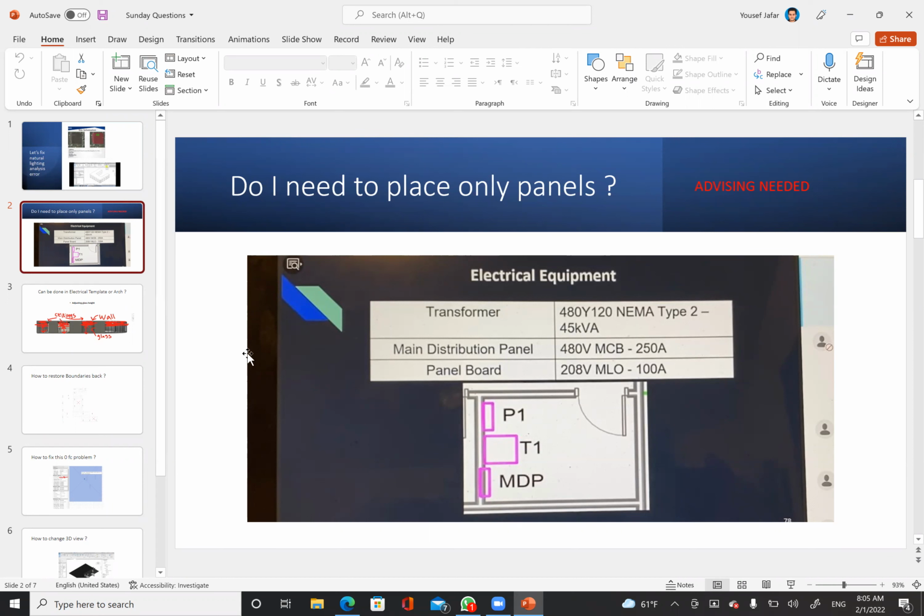Right. Actually, the standard distribution system that we are going to use is, like you said, 480 by 277 and 208 by 120. That is the standard that we have in mostly all places in the US, especially commercial buildings, because of the kind of fixtures that we use, either 120 volt or 480, 277. So it's going to be like that.